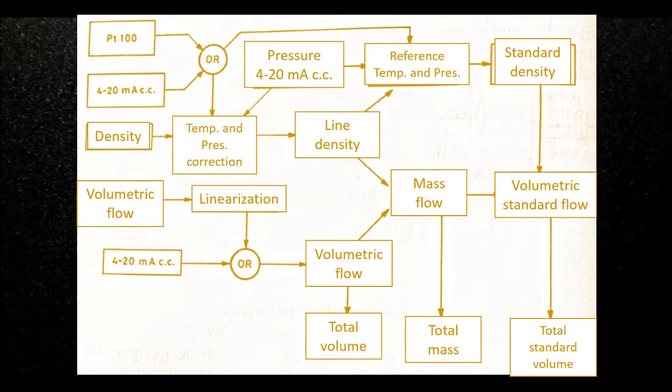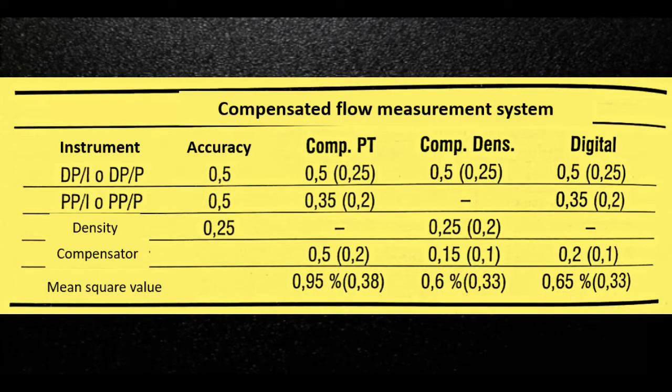They also have circuit test buttons, simulation of volumetric flow, pressure and temperature, alarms with indication of error codes, circuit calibration, and its programming. In each of these systems, the accuracy depends on the influence of the components used. For example, using an orifice plate placed in a special precast pipe can have an accuracy of plus-minus 0.5%. In this table are the accuracies that can be obtained with the previous sets without including primary elements or the final instruments. That can be receivers, integrators, controllers, etc.